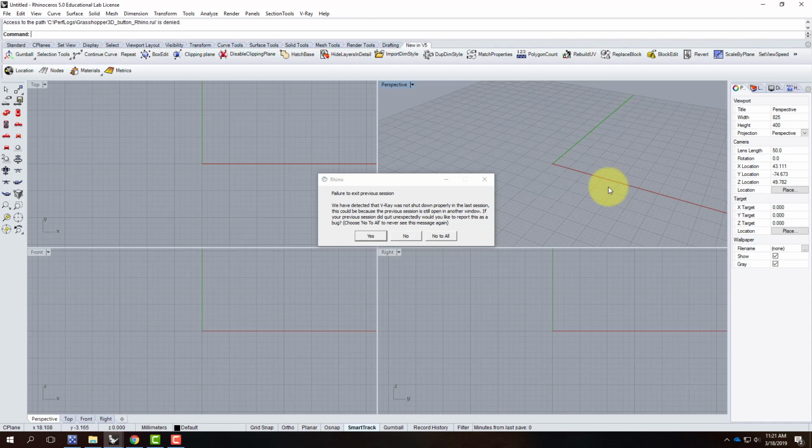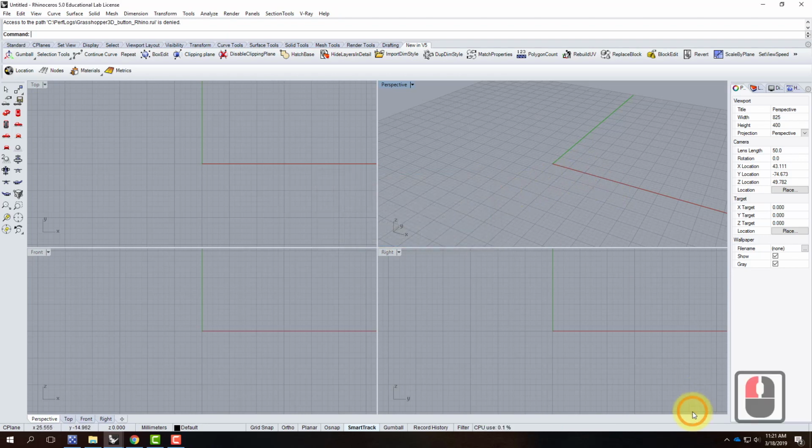Rhino can actually unroll surfaces as long as they are a specific type of surface. And that surface is called a ruled surface. And essentially what that means is at any point on the surface, so if I was looking at this as an example here, there is a straight line between one edge and the other edge. So the surface can twist all at once, but there is always a straight line. It doesn't ever bulge out. Does that make sense? So that type of surface is called a ruled surface, and that's what we're going to be trying to work with when it comes to these projects.